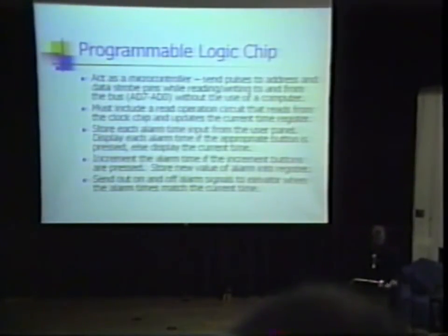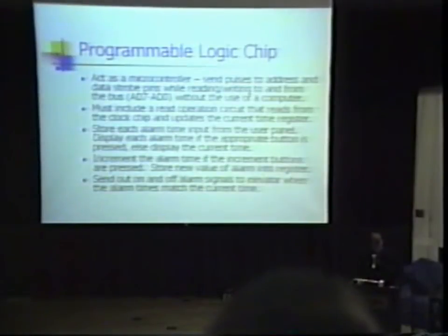The programmable logic chip is probably the most important component of this project. All the real-time clock chips that I researched were designed to work with a microcontroller. However, my sponsor was interested in using a programmable logic device to reduce the cost and parts count. So the programmable logic chip was to act as a microcontroller to send pulses to the address and data strobes, as well as read and write to the multiplex bus instead of using a computer.